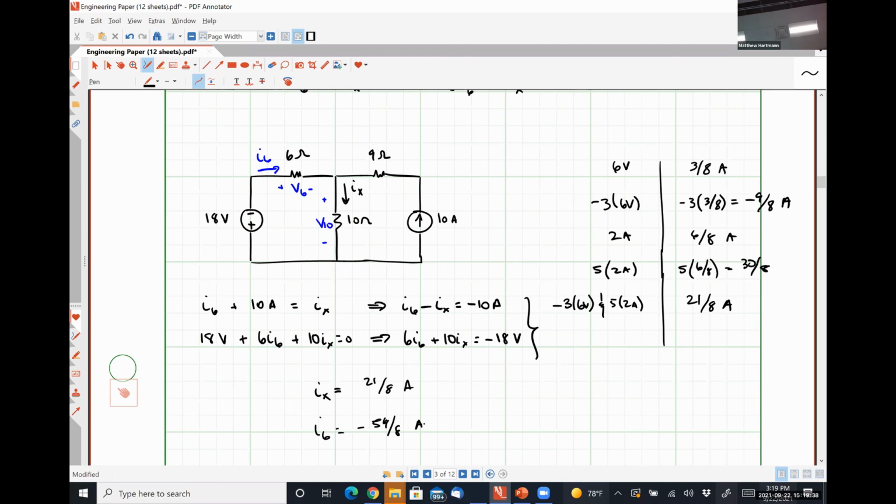Right? So that's why the concept of linearity can be such a powerful tool. We could actually work any linear circuit using only 1 volt voltage sources and 1 amp current sources, and then scale everything to find the answer for any possible configuration of input signals. Okay, that's a pretty dang neat thing. Any questions? Any other questions on this? I know it sounds weird, so I'm going to ask you guys to try to wrap your heads around it with the in-class assignment problem.